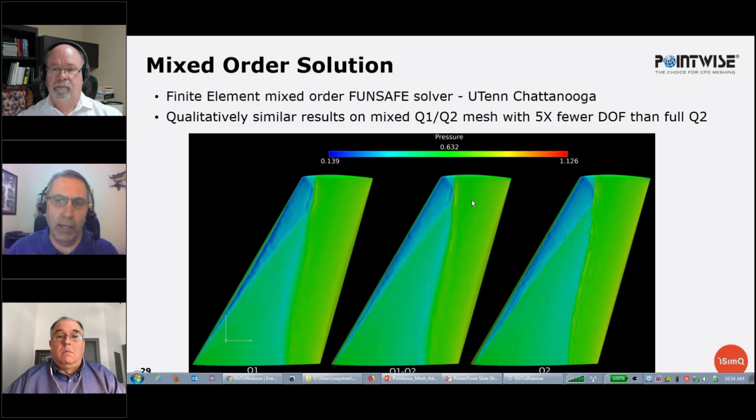And this would allow the entire region behind a bluff body, for instance, to be refined uniformly to capture those vortices. Now, if you had a longer period unsteady case, you may choose not to do that. You may choose to essentially track those features as they're propagated downstream in some large environment, maybe like a wind turbine or something like that. In which case you would only keep around a couple of point clouds, as we did in the steady cases.